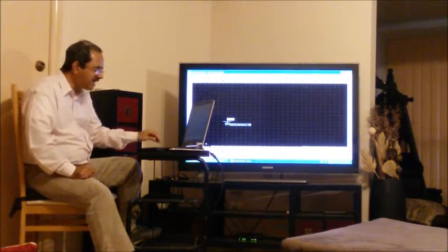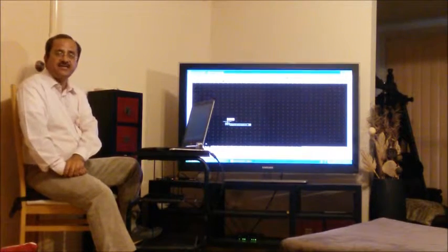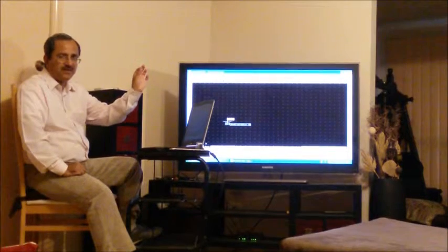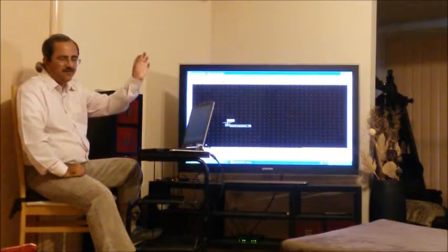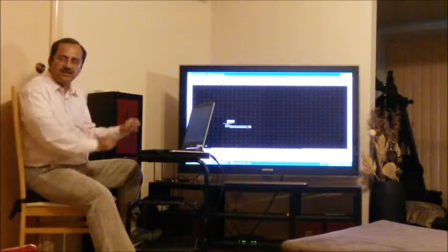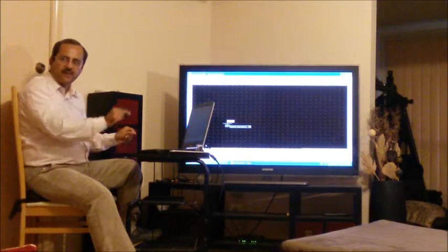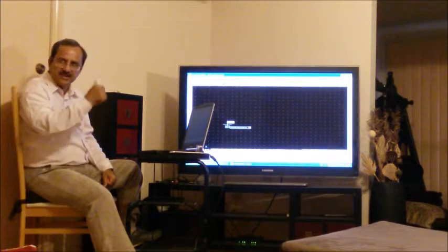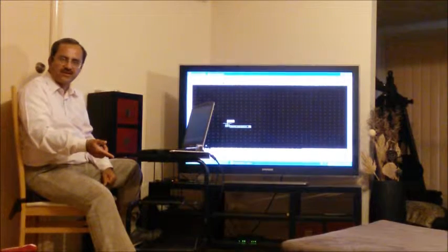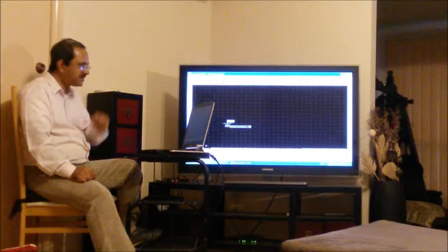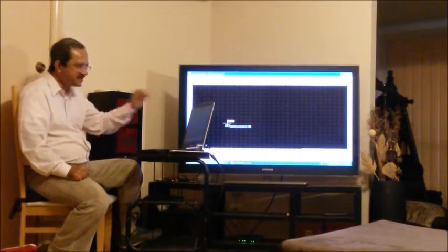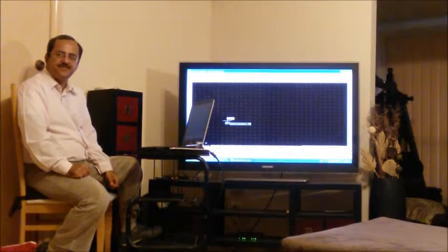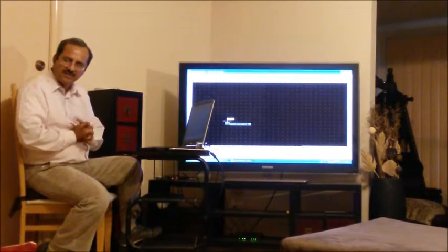Another way I can do is simply type the coordinates of that point. Let's say I want to start at a point where x value is 1 and y value is 1. So I will type 1,1: x value, y value. This is another way I can input the point. To keep things simple, I will just click on the first one. Now AutoCAD is happy. It turned out the first point.